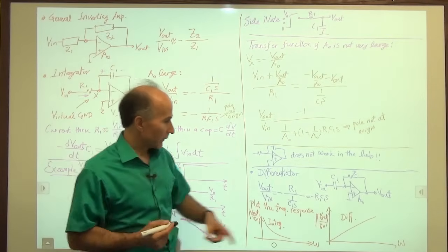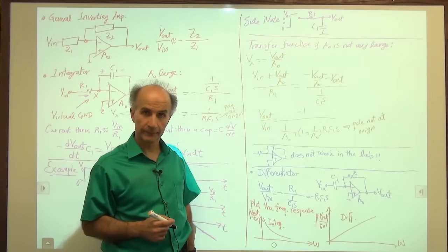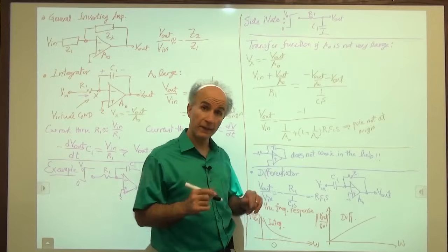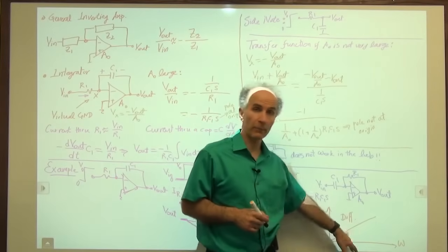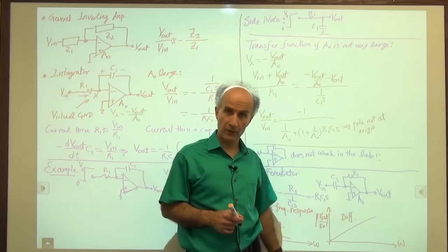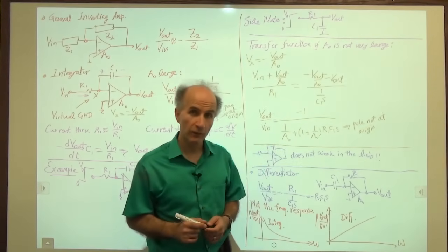All right, the fact that the differentiator amplifies high frequencies is generally troublesome. What it does is, if we have noise in the system at high frequencies, it amplifies it, even though we're not interested in noise. And for that reason, which is a little beyond the scope of this course, we rarely use differentiators.